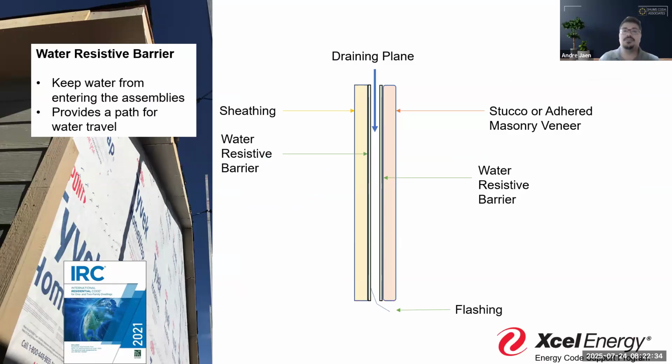It goes over your different hard coat stucco finishes. And then it goes over the water resistive barrier versus the bond break component of it, which is why you get those two layers of paper between the chicken wire there, that lath. But it basically gives a good explanation of how that's supposed to work in the overall system.